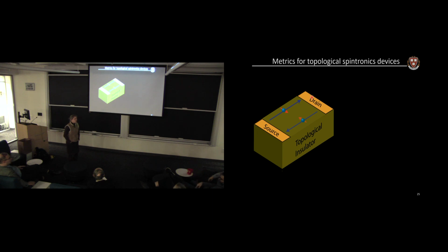So how did? Yeah. So the idea is that the spin current is protected, and what you would do is put this adjacent to some kind of magnetic material. And so you would use this as a generator of spin current, but probably the information bits would be in an adjacent ferromagnetic material. And the beauty of these materials is that just by sending a current, you can generate the spins that you want. And then those will couple into the adjacent ferromagnetic layer. Did I answer your question? Yeah, because otherwise it just seemed like you're still moving current around. Yeah, right. Okay.